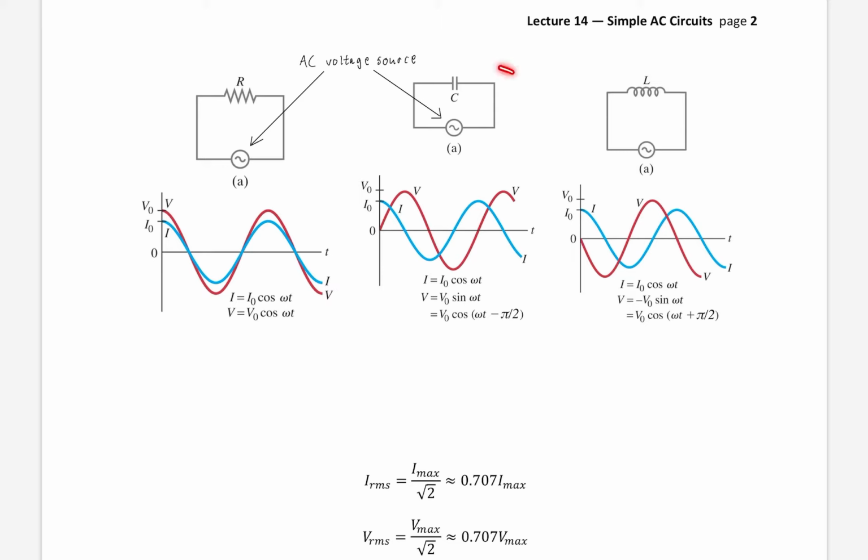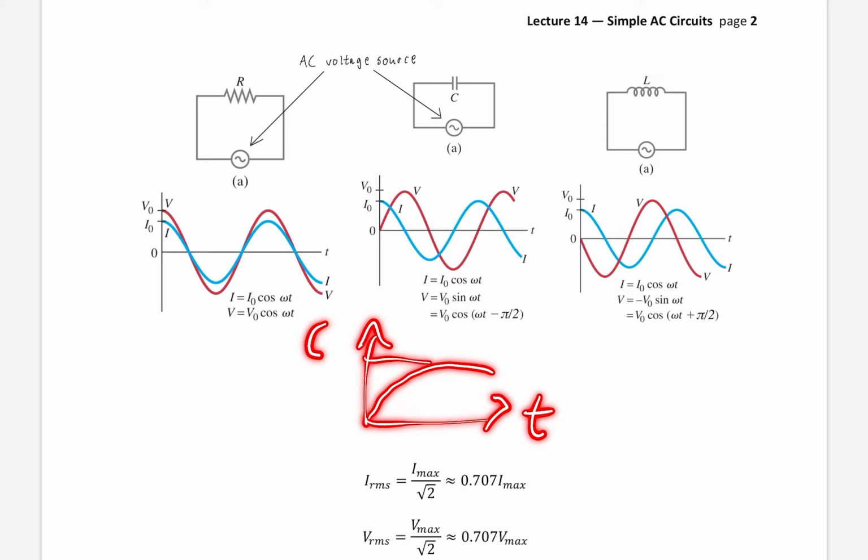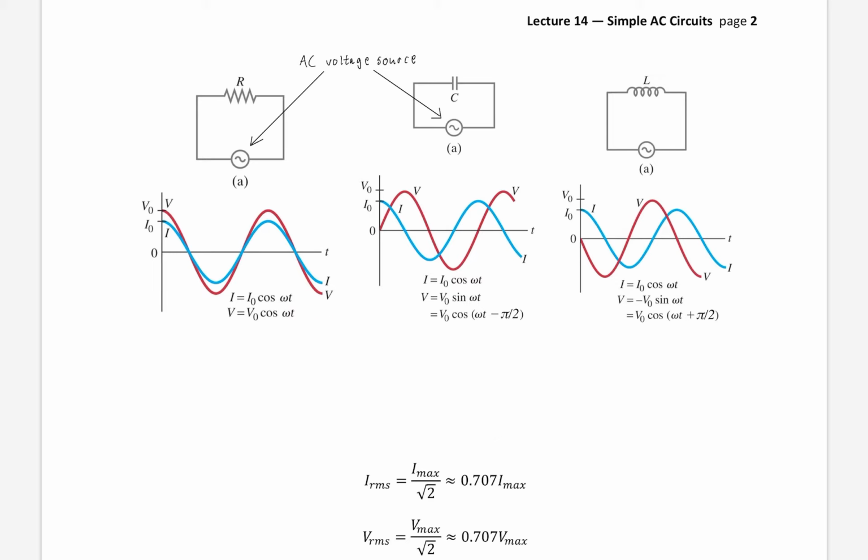Okay, well, the capacitor certainly isn't the case. Now, that shouldn't be a surprise because we've seen RC circuits before. We've seen that RC circuits have a time-dependent behavior. Charging up the capacitor, capacitors charge quickly at first and then more slowly over time, okay? Think about how they build up charge over time, asymptotically approaching with an exponential function a final value of maximum charge.